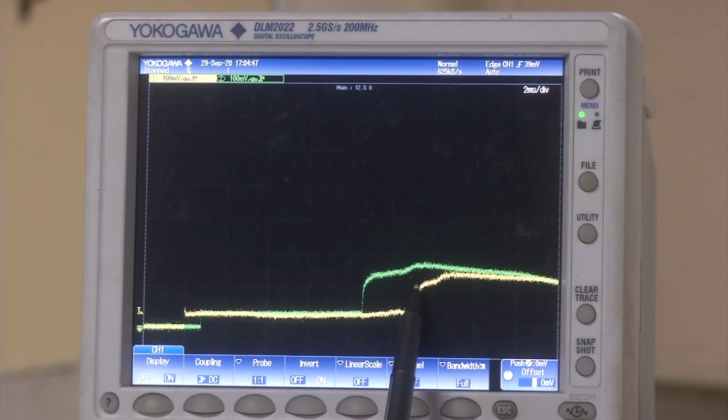And here, by the time the flow has already been contaminated due to the arrival of the contact surface, you do not see any steady region; there is a continuous rise in the pressure. However, at this particular time scale, some steadiness is seen, whereas in the first pressure transducer, in the reflected events, no steadiness is seen.